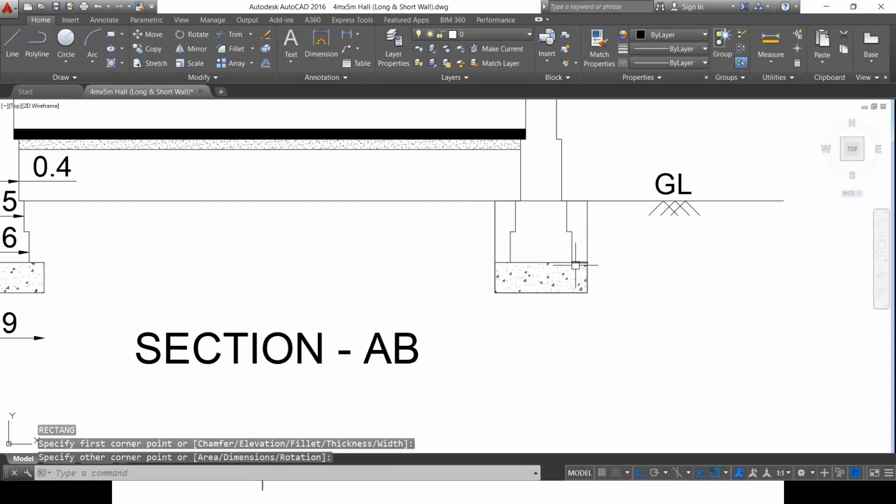I cannot do separate excavation for PCC and for the first footing and second footing, because though they are varying in size, we cannot do separate excavation as in the case of stepped footing or something like this, which is seen on the screen. We have to do the excavation all at once and then start filling the concrete, and then the first footing and then the second footing.